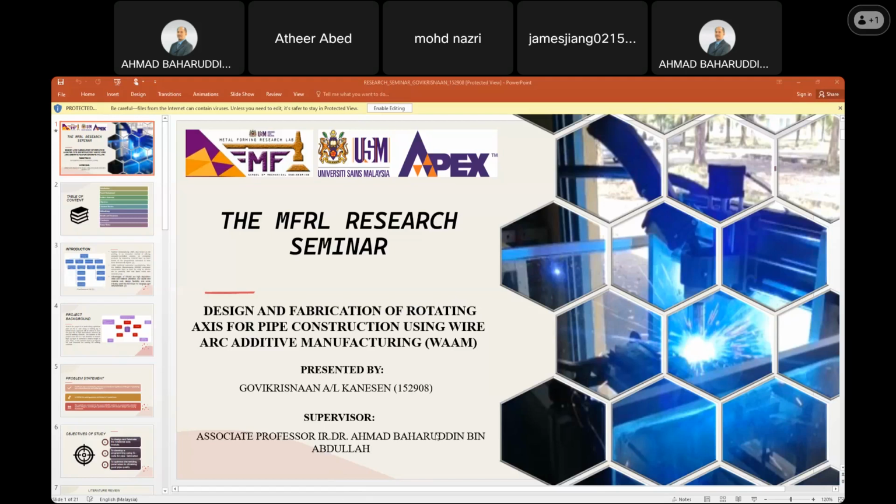So my project background: the goal of the project is to weld a long cylindrical pipe on the x-axis using a rotating jig. The helical shape approach will be utilized to form the pipe, due to the high dependence between the jig and the 3D welding machine. The initiation of the project occurred due to the Z-axis limitation to deposit layer by layer to construct a decent length of pipe. Thus, a new method needs to be figured out to improve the existing 3D welding machine.